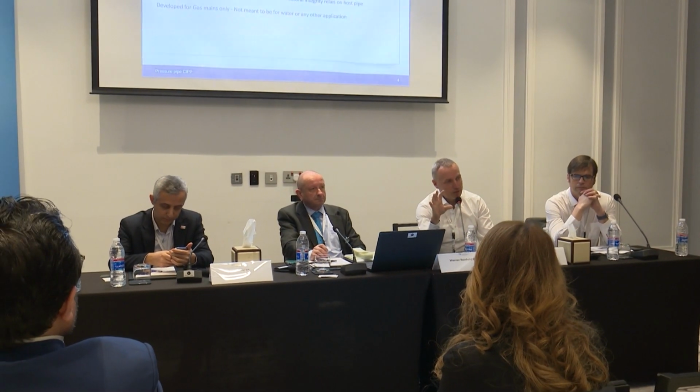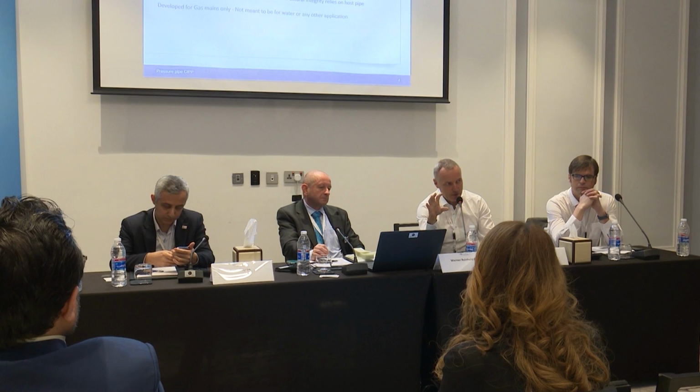When the pipe is new, everything is fine. They put the lining in there, and the lining was kept flexible. So when you have an earth movement, the lining stays inside the pipe, bonded to the existing pipe, and it bridges over the joints, so the joints will not be leaking anymore. That's where the entire idea of pressure pipe lining comes from.